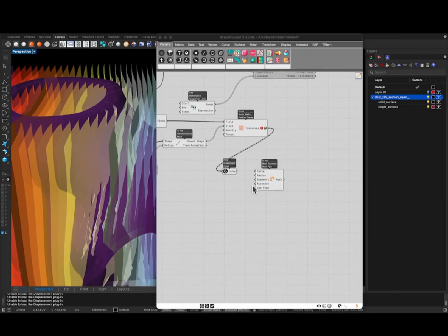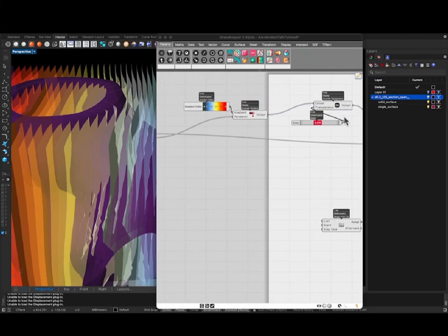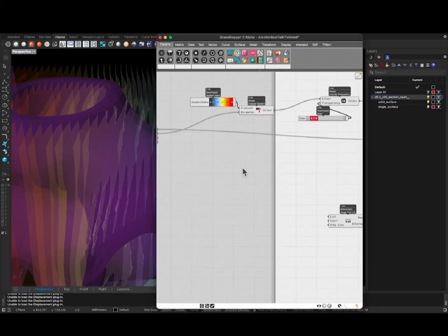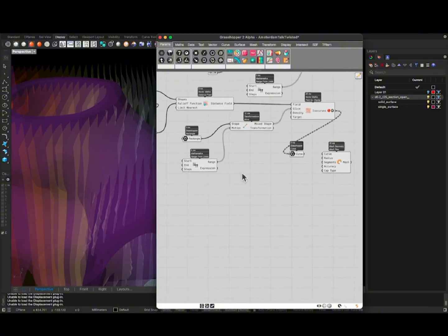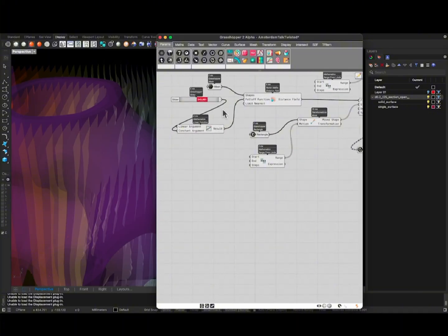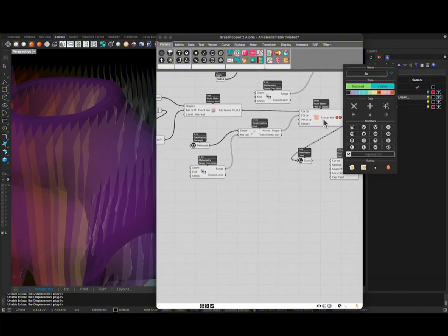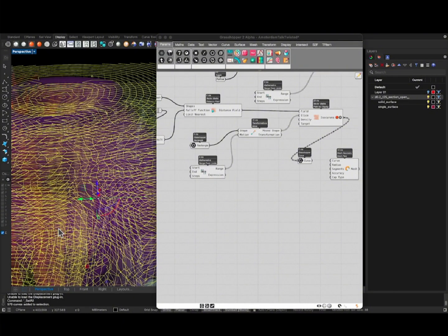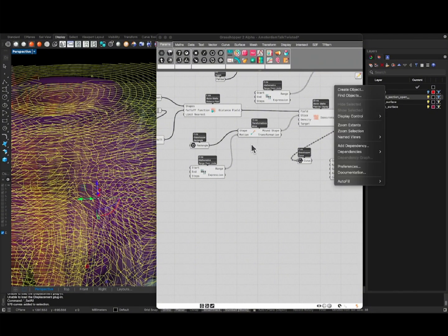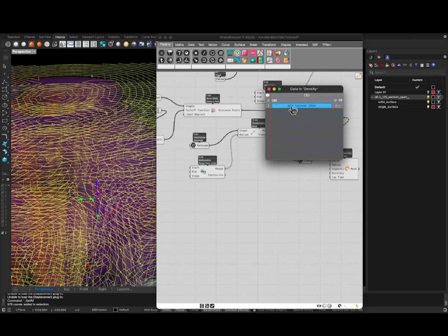We would have, so let me increase the transparency of these ones here. We would, for example, in Grasshopper 2 just have this mesh that we have referenced. You have a distance field, you have a fall off, and then you have the isocurves. For some reason, I have to bake them here right now due to some display glitch, but you can still see what's going on. I can increase the density a bit.